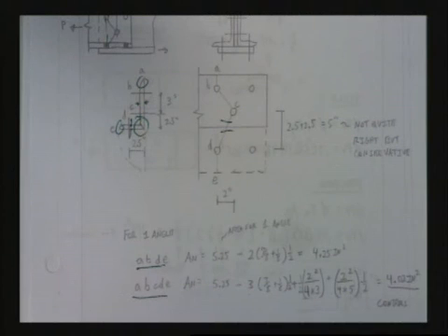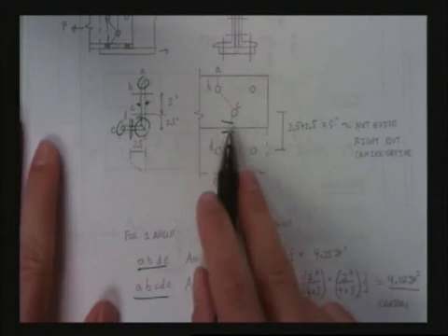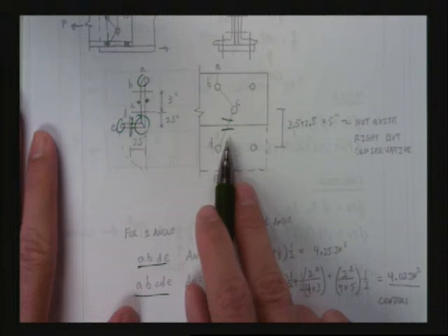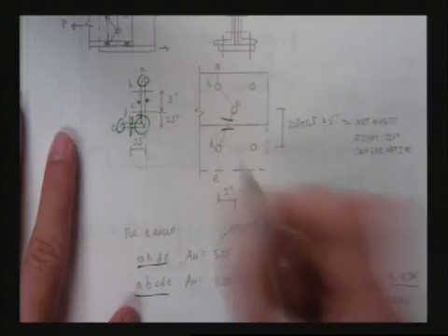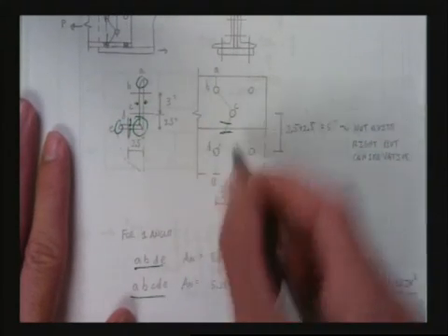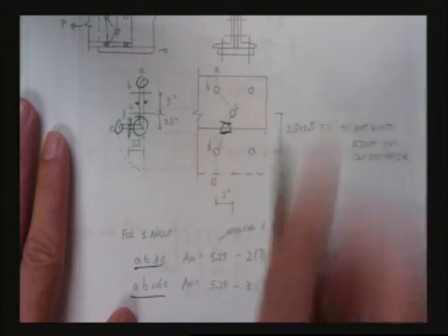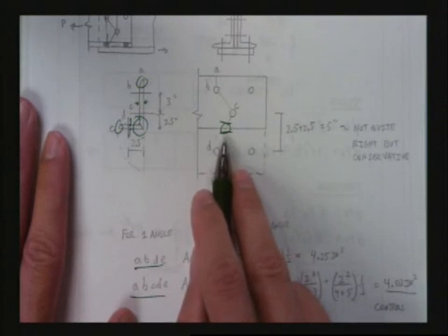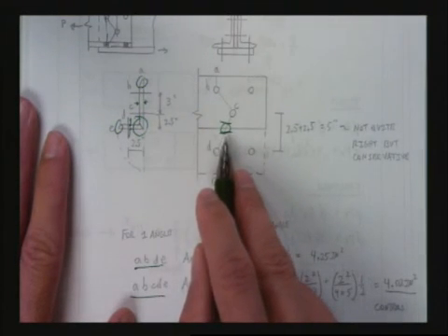But what I'm going to say to you, and this is advice please remember when you're doing your homework: when you can do things that are conservative, that simplify problems, do them. Because if not, you'd have to come up with some way to take into account this thickness. I'm going to give this extra area a little bit more benefit, say add about 15 or 20 more percent to this area. Maybe one could argue that, possibly.